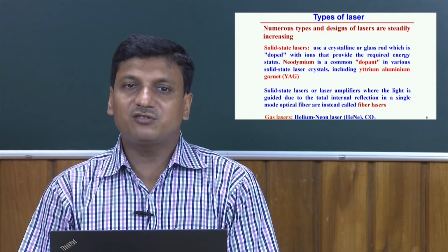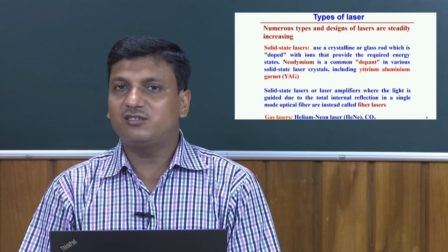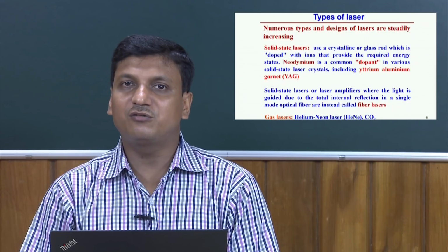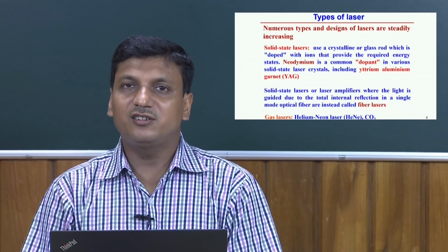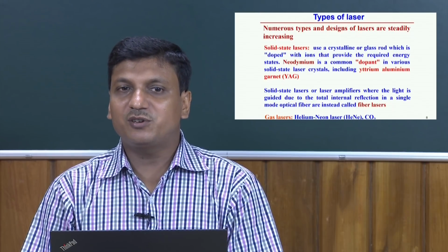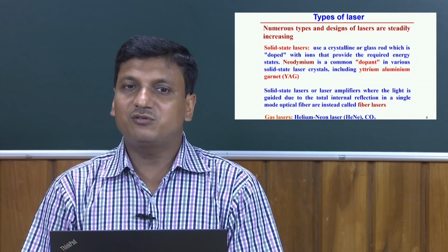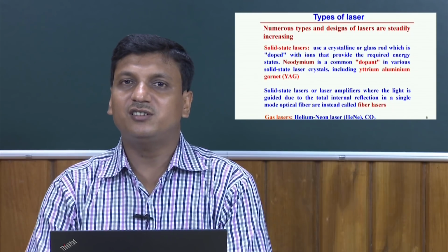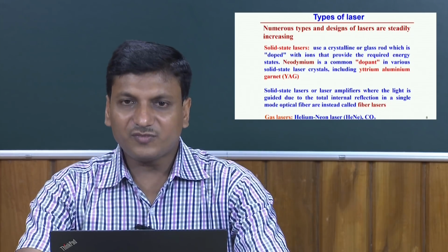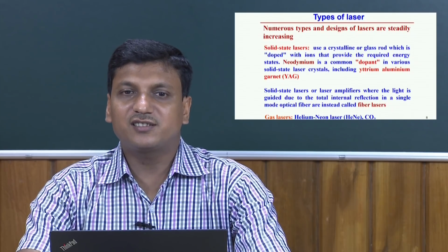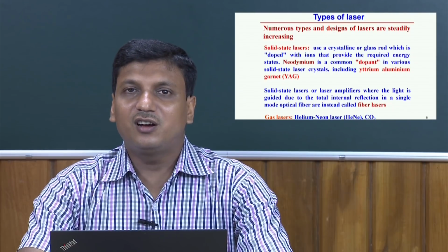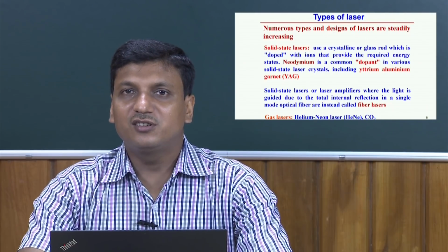Of course, the fiber laser is a solid state laser, but the only difference with respect to the others is that an optical fiber is used to conduct all the internal reflections. So, in that sense, with respect to the Nd-YAG laser or other normal solid state lasers, the concentration of the light can be more in the fiber laser. The other type of laser is the gas laser, and we commonly use CO2 gas lasers or helium neon lasers. Here the lasing medium is the gas.